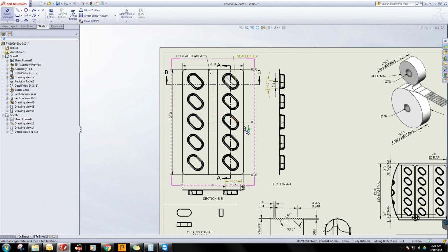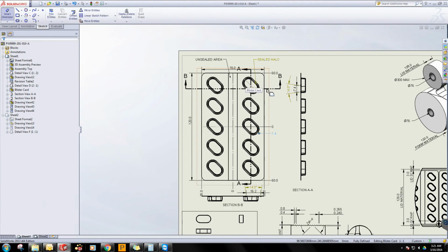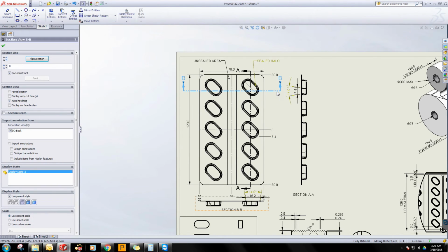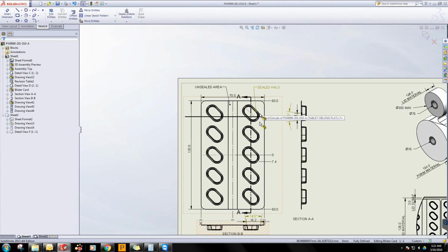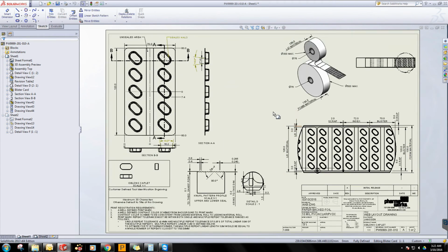This case is going to be an interesting example because it's all at these odd angles. If that's the case, you might as well go ahead and delete these or adjust them, which I can do here. It's a simple thing: editing a sketch and then just orientating and making it collinear with that point, and then you've got it. So I'm not going to do that for the sake of this tutorial. It's simple enough, and any designer knows how to do that.